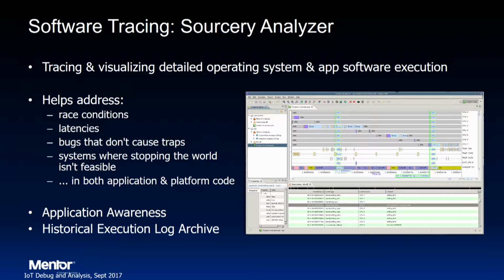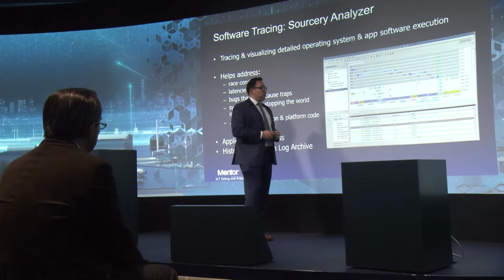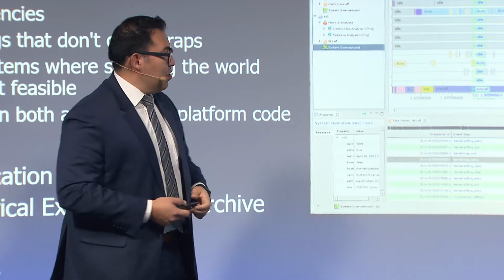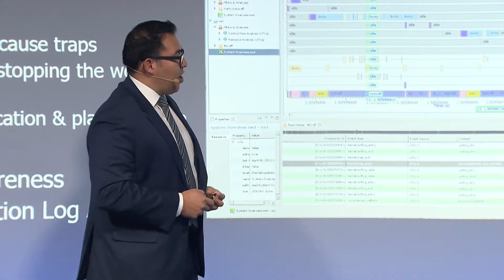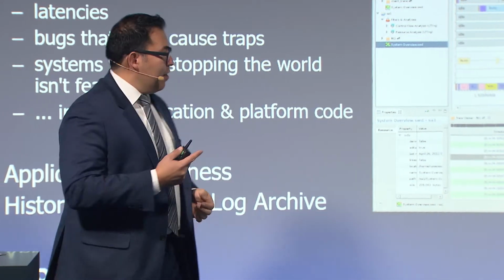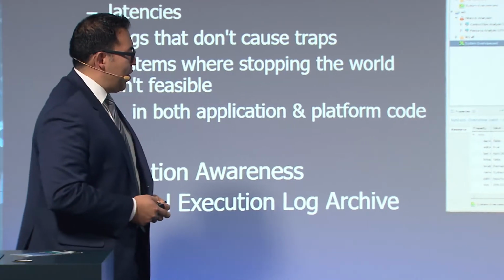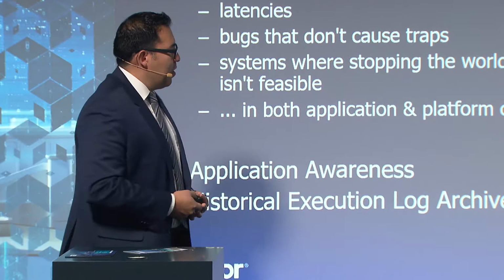Now, we've zoomed in very closely here on a very short timeline. So the distance between the green lines here is, for example, 1.5 milliseconds. So it's a very high level of detail for extracting behavior of multi-core systems and finding things like race conditions, for example. After the CPUs, we have a number of traps, and the soft IRQ, for example, is used in, say, Linux for trapping and interrupting the various processes on a system. And below that, you would have process and thread state and a number of other embedded system variables that are important for optimization of the system.